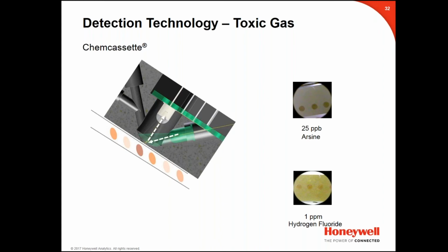Right. So the system is based on colorimetric technology that is capable of extremely low detection limits for a specific gas. It can be used very successfully in a wide variety of highly toxic substances, including diisocyanates, phosgene, chlorine, fluorine, and a number of hydride gases employed in the manufacture of semiconductors.